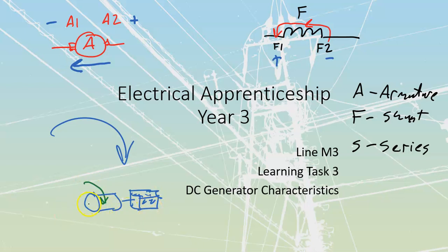This just makes sense. If I were to open this up, I'm hardly ever going to remove the engine blocks so that I could look into this end of the generator. That would be impractical. Most of the time, I'm going to stand over here where the engine is not in the way, and I'm going to look into this genset. So for clockwise rotation, observe from the non-drive end.